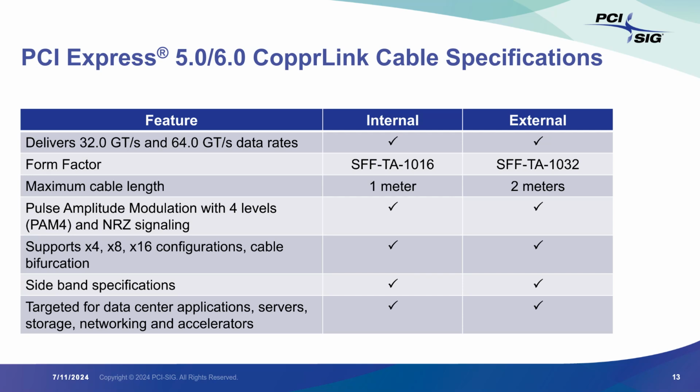Similarly, SFF-TA-1032 was a new project in SNIA that was initiated in collaboration with PCI-SIG, also formerly known as the CDFP form factor. Internal applications usually do not require as long a length; it's limited to a max length of 1 meter in the specification. For external, the specification is currently limited to 2 meters. Of course, longer can be supported with various cable options, but given the data rate and the Nyquist frequency of 16 gigahertz, specification details are provided up to 2 meters.